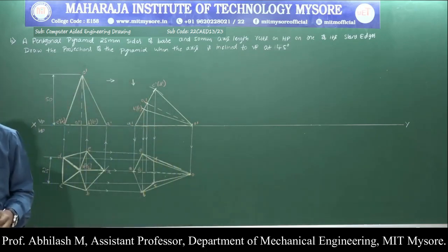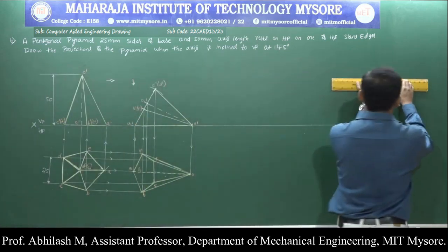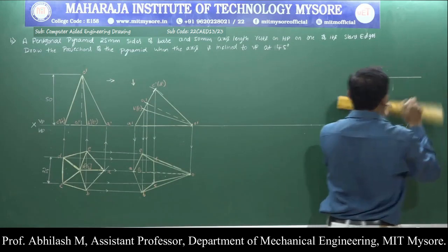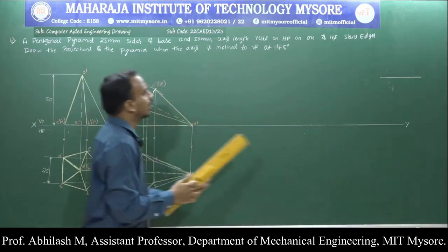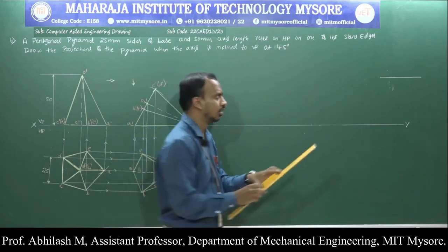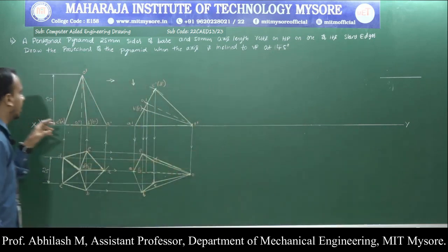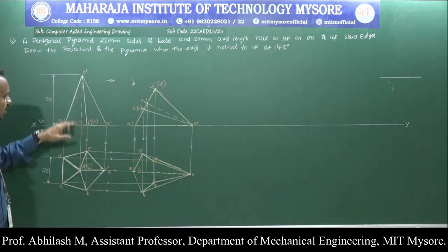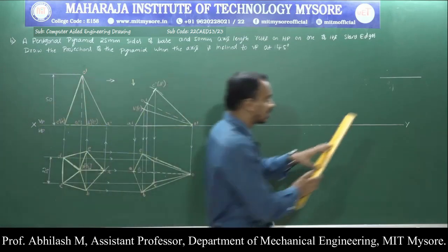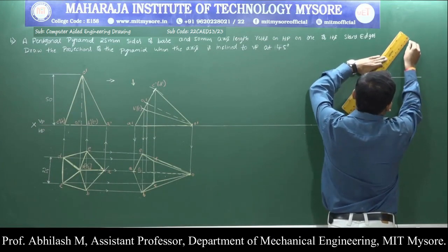First we are supposed to draw the locus. Let us roughly draw a locus. And for the given angle, that is 45 degree, let us draw a line. Let us draw a line of length, basically axis length, that is O dash O1 dash initial. How much is it? 50 millimeter, such that we are going to obtain a locus point again.